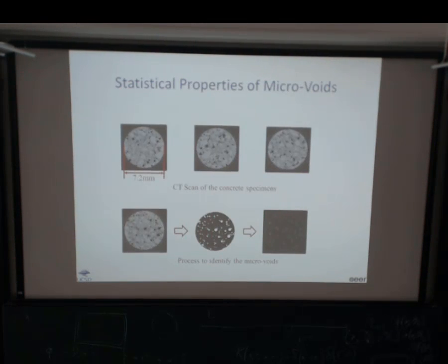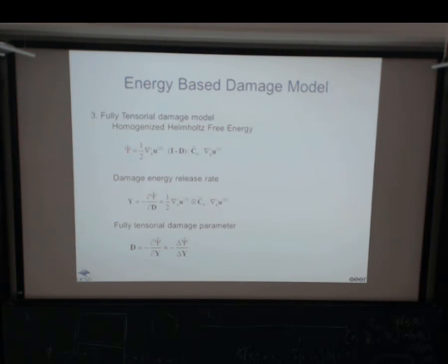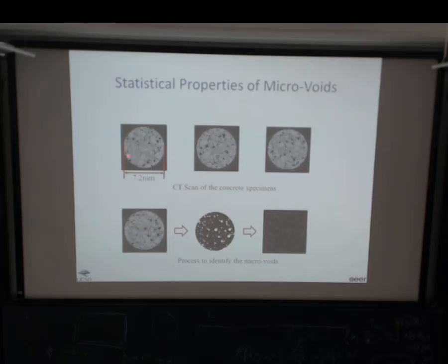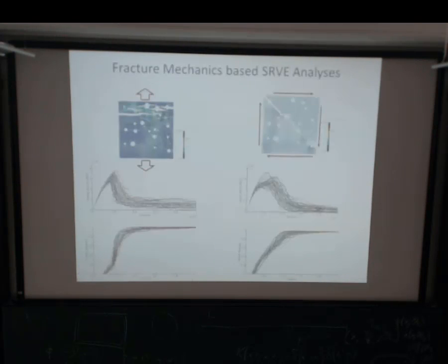All right, so with this, I just show you some examples. So here, you take different samples, and of course, as I said, different samples with different microstructures, then you get different damage curves. Right? So you can do this entirely based on the real material images. Here, we take 100 samples, so you get 100 curves.